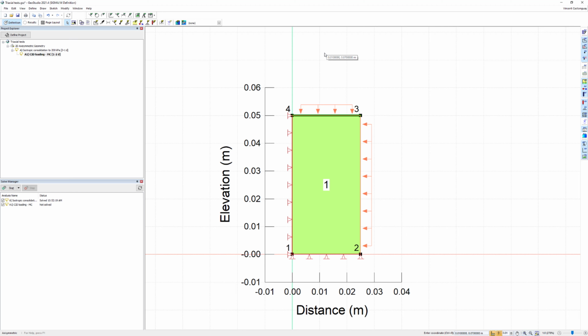The normal stress boundary conditions of 200 kPa are also still applied to the right and top side of the sample. Should these boundary conditions remain in place as we simulate the triaxial loading? After all, during the loading, the cell pressure would continue to restrain the sample in the laboratory. The answer is no. The stress boundary conditions should be removed.